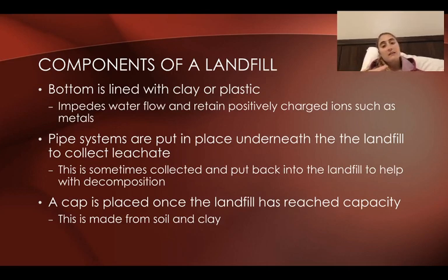Then what they do is they line the bottom of the landfill with something like a clay or a plastic or a combination of both in order to prevent anything from seeping into the soil. This prevents water flow, and it retains these positively charged ions. Remember, we said there's this cation exchange that's happening. It prevents things, and metals, from getting into the soil, which we don't want. We don't want that leachate to get out. Then, under that, there's this pipe system that's put into place, and that's what's actually going to pump out all of this liquid, this leachate that's going to be produced from all of this trash that's been sitting here, from all this MSW that's been sitting there.